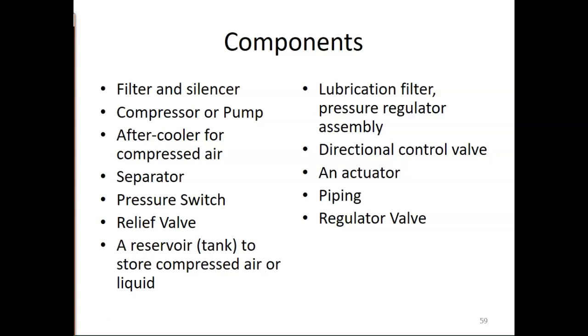Hydraulics specifically have to have some form of a reservoir or tank. You can have them with air compressors. You don't always have to have them with the compressors, but you have to have some form of it with a hydraulic system. If you have one with a compressor, it stores air so that you don't have to wait as long for more compressed air.